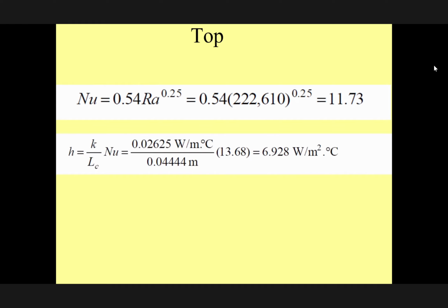Therefore, now you have this value. This is the heat transfer coefficient from the upper part of the plate to the outside. Okay. Therefore, you can simply calculate. Now you have h, you have the temperature difference. You can simply calculate how much is your heat transfer from the top. h is this value. You assume the temperature of the plate, okay? But now we have to calculate what exactly it is, okay? Because the whole idea is trying to calculate the surface temperature, okay?